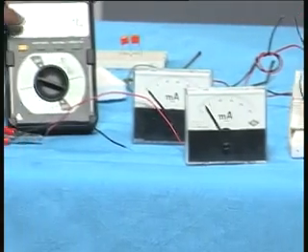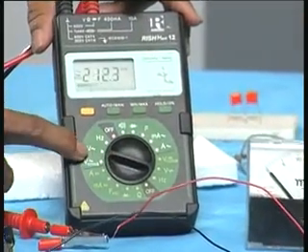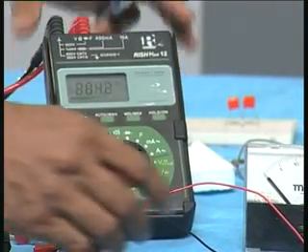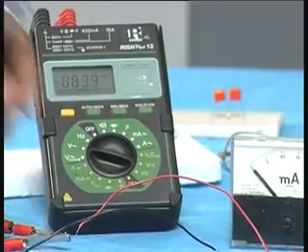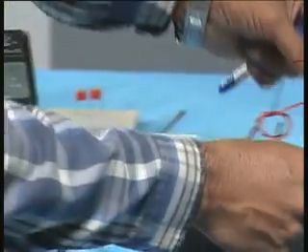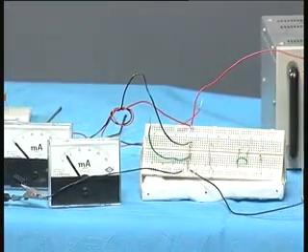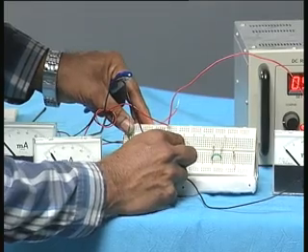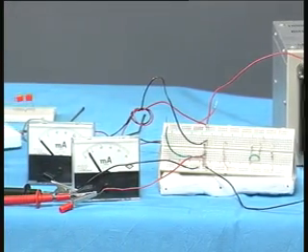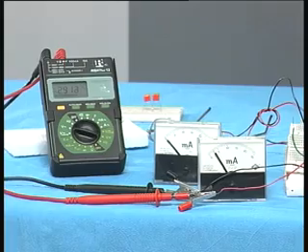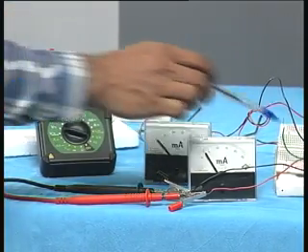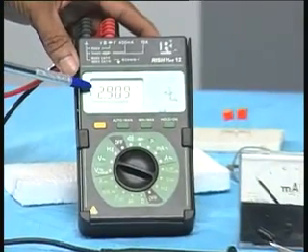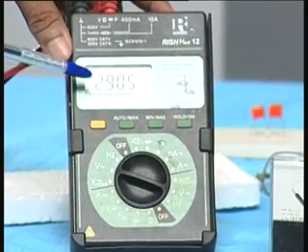Now, I have a voltmeter which I have connected, and it is now measuring DC volts between these two terminals, and now I will use this to measure the voltage across one of the resistors. For example, I connect the bottom to the ground, I take the other wire and connect it to the midpoint. If it is connected to the midpoint, then it is measuring the voltage across the lower resistance R2, and you can see the voltage is 2.9 something, which corresponds to really 3 volts approximately.